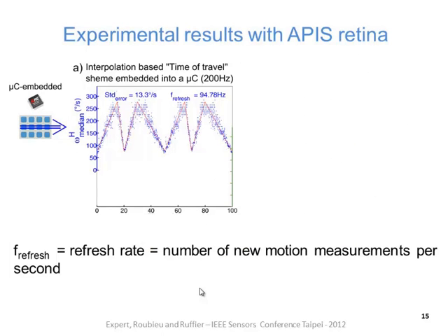And we did the same experiment, but now with the processing embedded in the target. Everything was in the target board I presented. We obtained even better measurements than what we were expecting, with a dispersion of 13 degrees per second. We also measured the refresh rate of the sensor, which corresponds to the number of measurements per second. We obtained nearly up to 100 Hertz, which is really good for us for robotic applications, for controlling a robot, like I presented at the beginning.